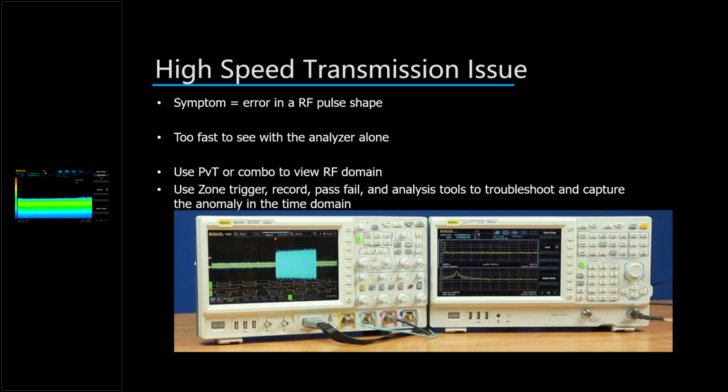As you can see here, we're in a density view, and you can see about once a second an RF pulse is happening, and you can tell we're in the 2.4 gig band, looking at 40 megahertz wide. There's a frequency hopping FSK signal here, moving around the 2.4 gig band. We're having an occasional issue with some of these pulses, so let's look more closely.